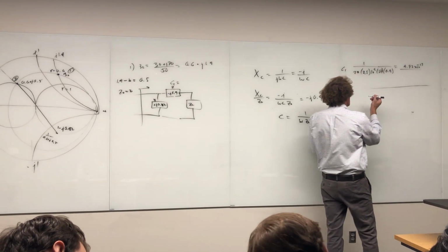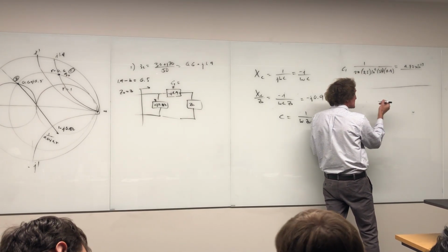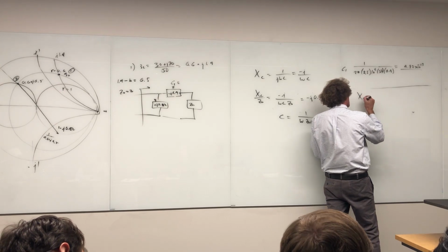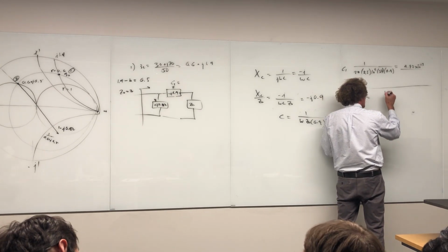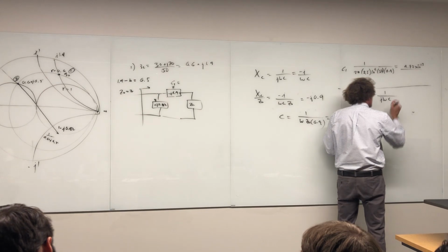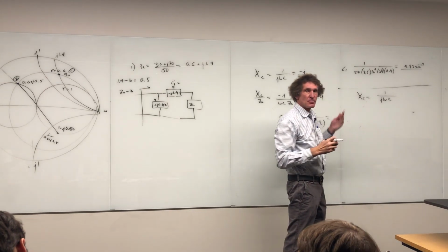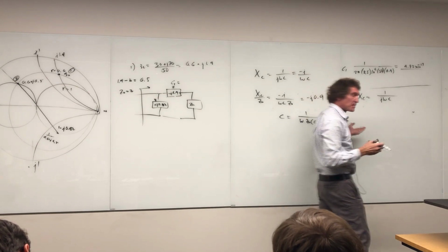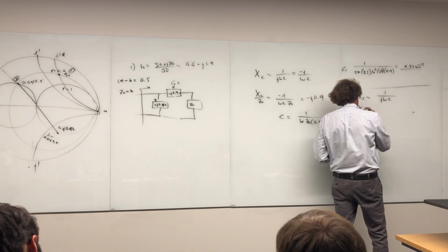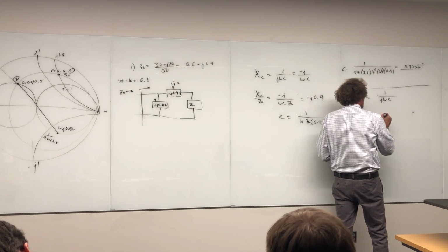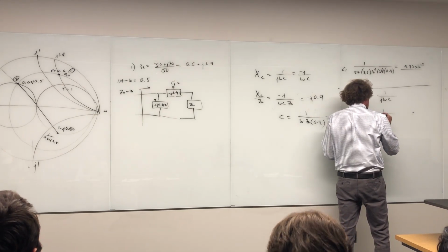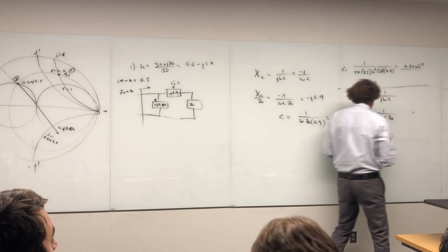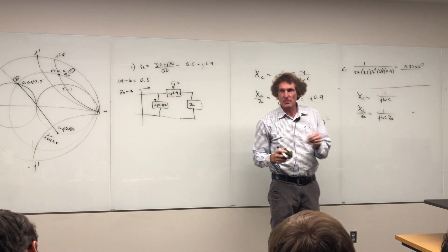So everybody on. So for the second one, it's going to be a capacitor. First, I always start with capacitive reactance, and that's 1 over J omega C. That's one of the most basic formulas you learn in circuits, right? You always go with what you know for sure. When we normalize it, X sub C over Z naught is going to be equal to 1 over J omega C Z naught. Now we have normalized it. We have to normalize it.